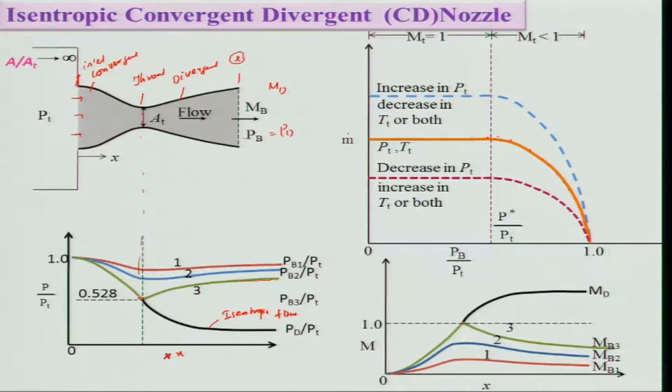If you look at this, the critical back pressure is what I call the critical point, or choked point, right, and this is equal to P equals 0.528 PT, that is critical, and sometimes we write it as P star. This is because of the choked condition or the sonic flow, right. That will tell you where it is choked. If my pressure at the throat is equal to 0.528 PT, then it is choked.